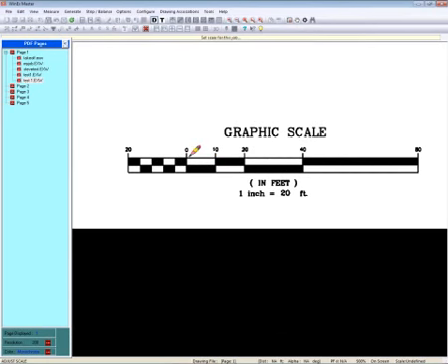And by the way, if you want to get very, very accurate, we have one more tool here. If you hold your right mouse button down when you're in the measure mode, when you see the pencil, it'll zoom you into almost pixel level so that you can drop that crosshair when you let go of your right mouse button right at the intersection of those two lines.